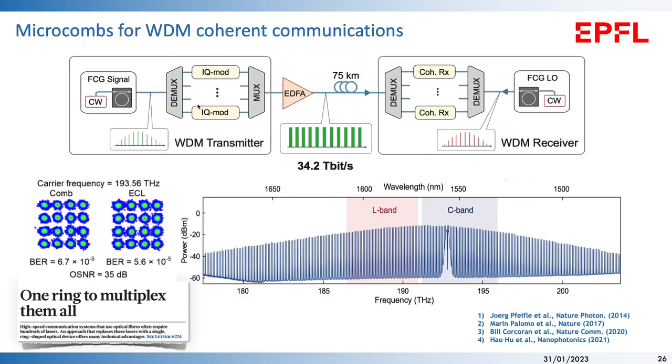For another application, for example optical communication, you have the optical frequency comb with 100 or 200 gigahertz FSR. You can use this as a WDM optical carrier to transmit your signal. But then again, if you look at the link, there are a lot of small triangles along this link to amplify the comb lines.